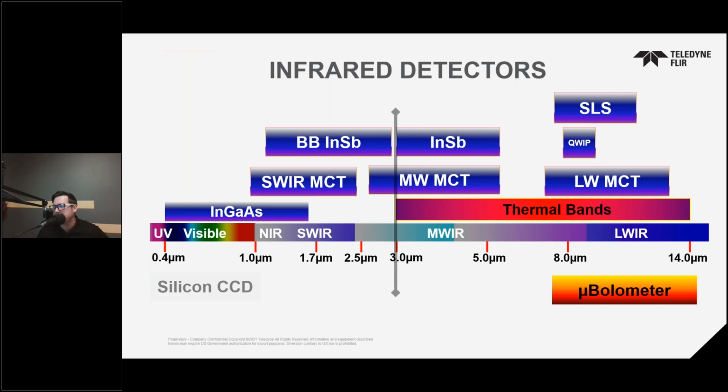It should also be noted that just because a material can have a response in a wavelength doesn't inherently mean that it's the most ideal for that wavelength. For example, InSb can get down to 1 micron, but the response isn't very good. So since we're talking about spectral filtering today, if your application had a requirement to capture data at 1 micron, discrete, I wouldn't recommend InSb until we work through all of the other test requirements to understand where the 1 micron requirement fit in the overall priority of the capture there.